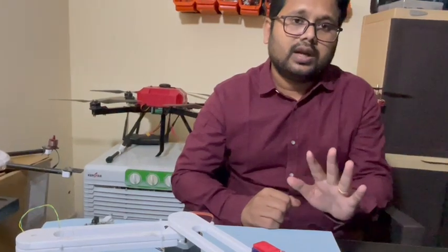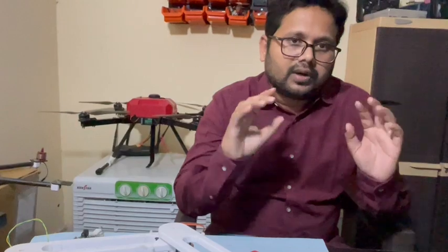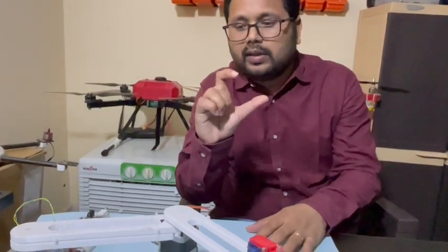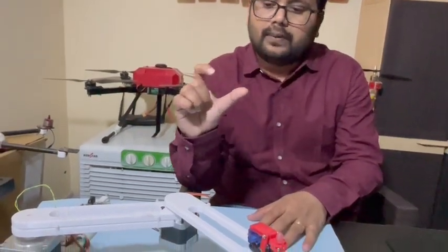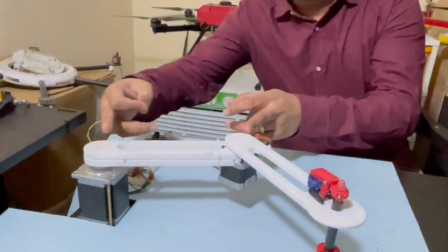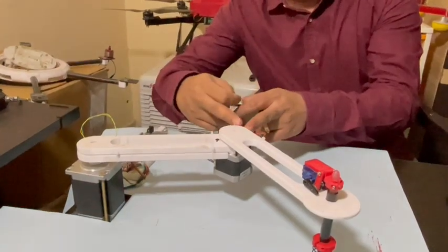This is your first introductory class about robots, so I will explain very slowly. I named this robot a two-link planar robot manipulator. What is the meaning of two-link? The word link came into the picture. A link is the simplest member in a robot, and the simplest member of this robot is one link, from this location to this location.